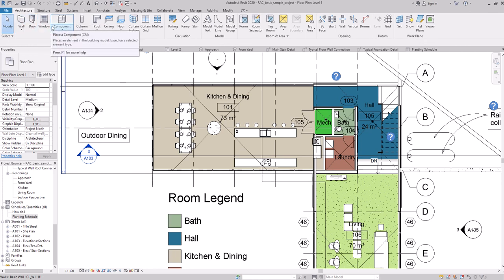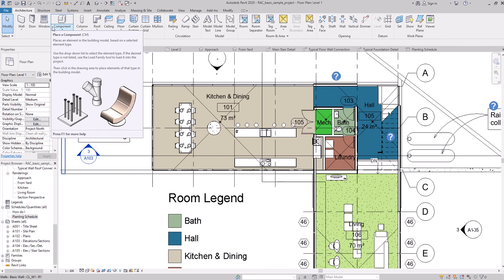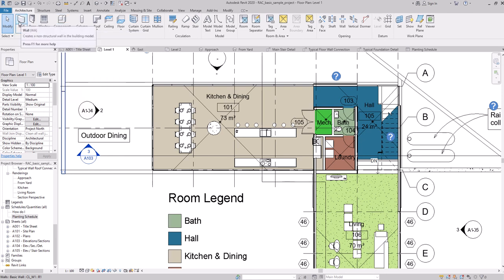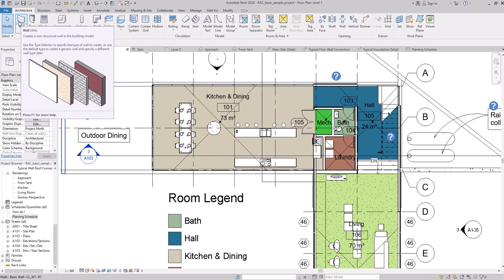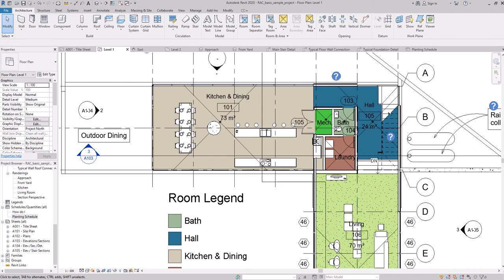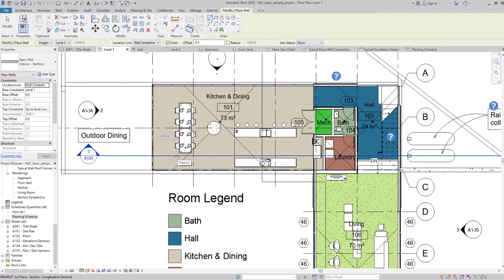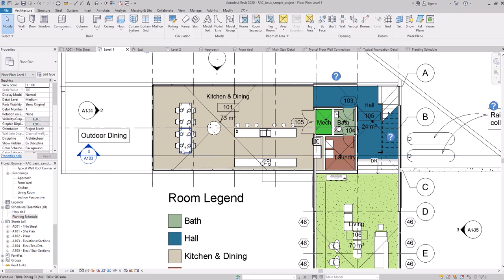In AutoCAD, we used to write the command that we want and press enter for it to open. In 3ds Max, we didn't have this option, but in Revit, we have a similar option. If you can see here, for example, when I go to wall, after wall it's written WA. So no need for a command bar or anything. You can just type WA and it will open the wall command. Okay. No need for enter, no need for a command panel or anything. Just type the shortcut and it will open it for you.